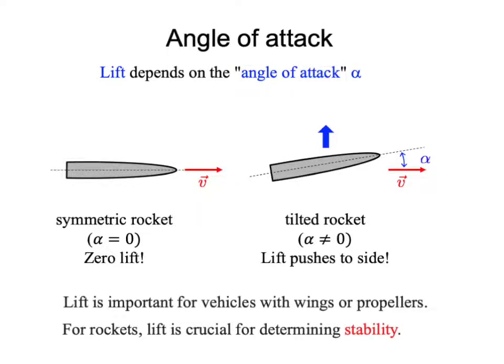Now, lift is very important, of course, to anything that has wings or anything that is pushed through the air with a propeller. It's the lift force that counterbalances weight in an airplane in level flight, and it's also, a little bit less obviously, the way that a rotating propeller pushes against the outside air. For rockets, the key thing about lift is that it determines the stability of the rocket in flight. And stability is a big deal.